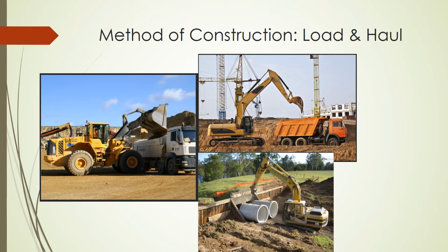The next method of construction that we're going to look at is the typical load and haul, and this is seen the world over and it's quite familiar. You've got loaders, backhoes or excavators, as you see in the top pictures here. They basically load the fill into the tubs of the trucks. The trucks travel down quite serviceable roads or serviceable temporary roads, unload the fill into the project where your graders and your rollers and whatever else spread it and compact to the specifications.